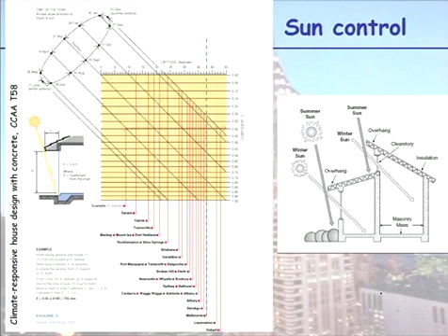So here is who needs a computer package. Here in this one A4 page, we can work out what sort of awning, how far out to make our awning in order to keep out summer sun but let in some winter sun. Because of that difference in the sun angle, you want to put awnings on houses so you can keep out all your summer sun but let your winter sun into your building.